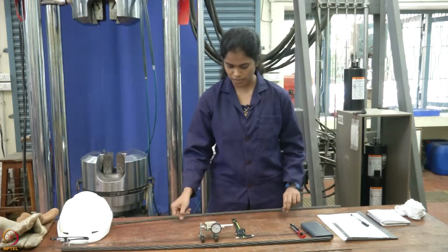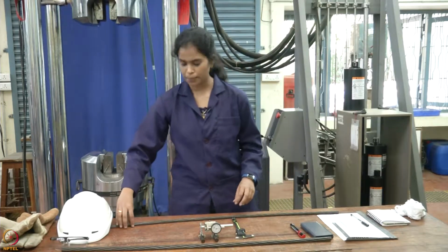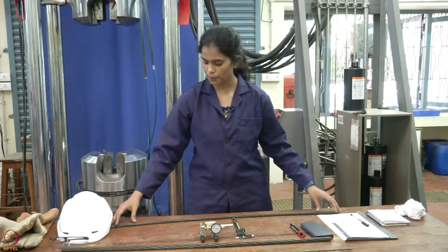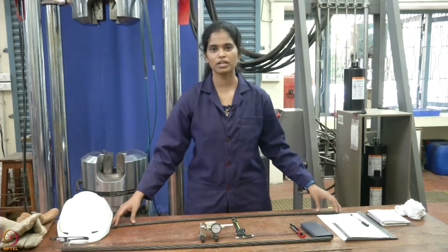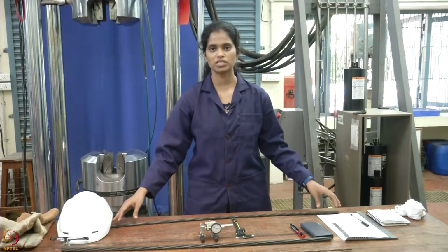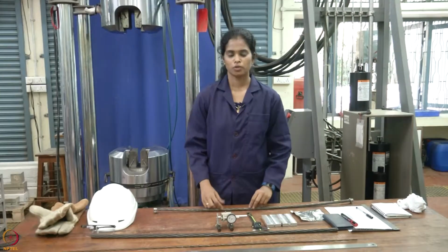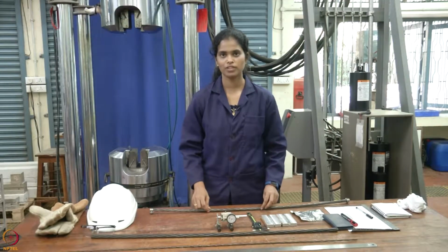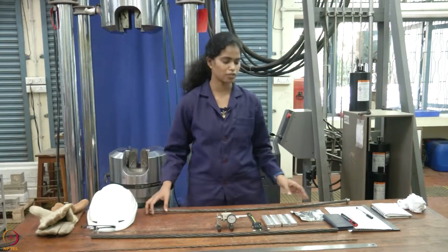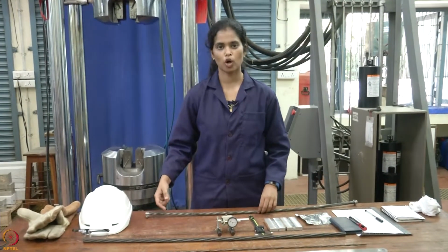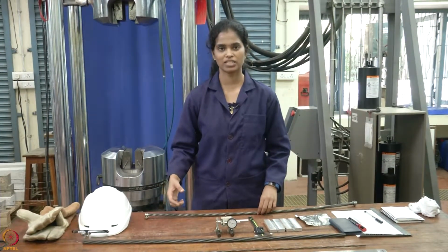Once the gauge length is fixed, we can prepare the gripping portion of the strand. For any tension test, gripping is very important because we need to avoid stress concentration near the wedges. When we apply lateral pressure while gripping, that will induce stress concentration and that may affect the result. So, once we get the dimensions of the strand, we will prepare the end region of the strand for gripping in the machine. We need to be careful while gripping because we need to avoid stress concentration, which will affect the results.